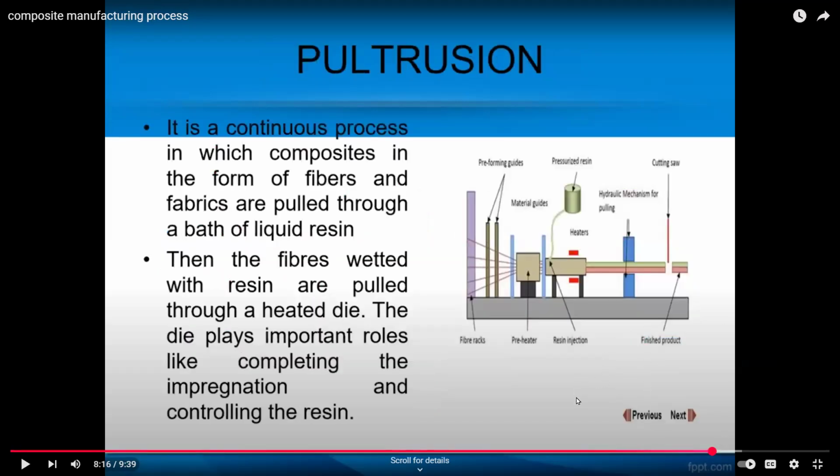Then there is pultrusion. Pultrusion means that we have a very special die, and fibers and resin system go into this die with a lot of heating, and since it's a plastic, this structure is immediately cured and becomes solid. Here the fibers and resin are mostly liquid, but once they go through these heaters, the products become solid. It is called pultrusion, not extrusion.